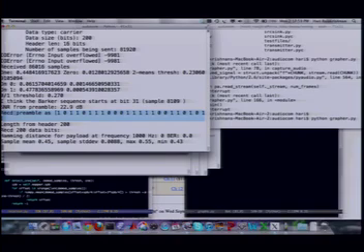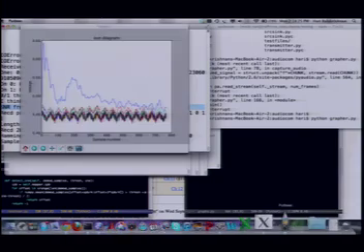We also plot out the signal-to-noise ratio of the transmission, and that shows up there. If that signal-to-noise ratio is something like 20 dB or 15 dB, things are fine. This system doesn't really work below 15 or 10 decibels. It means that the signal-to-noise ratio is too low, which means you either have to yank up the volume or you have to go to a quieter location, or, and I'll explain this, you have to change some of the parameters in the program. Now, what does this graph look like?